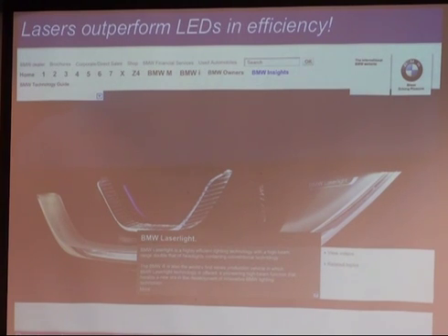The other very cool thing is these photonic devices based on compound semiconductors are designed at the quantum mechanical level to emit light, and that we understand. You can switch it on and off, or you can modulate the light at close to 100 megabits or almost a gigabit per second. You can have the light on all the time, but with a little modulation, and that can also be used to transmit data.